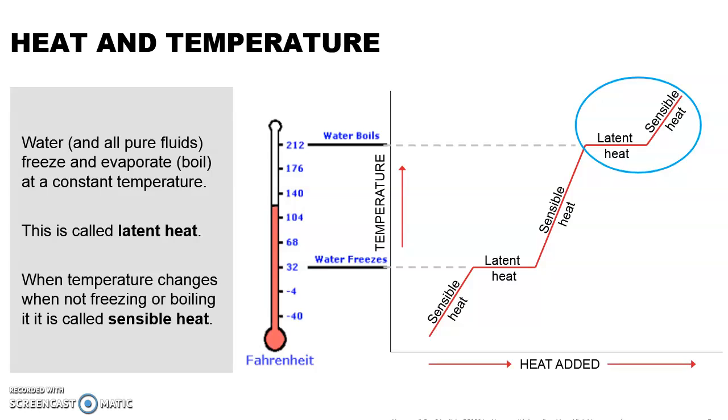In fact, at atmospheric pressure of 0 psig, R22 boils at minus 41 degrees Fahrenheit. This is why technicians have to be very careful when taking hoses off systems. That cold refrigerant can burn your fingers. In fact, one of our team members actually has no fingerprints because of all his years doing HVAC service.